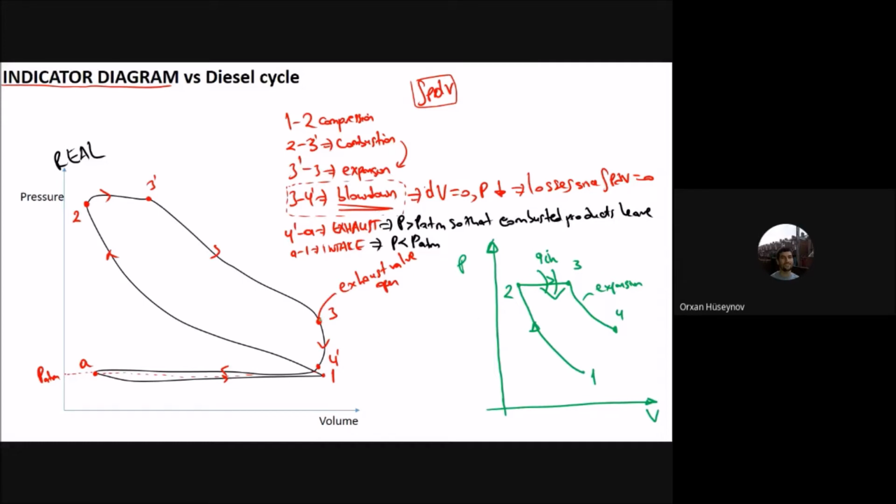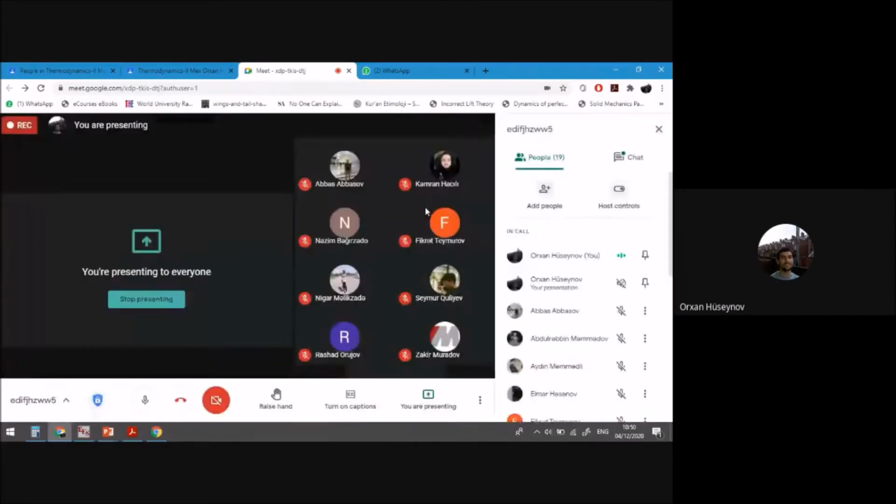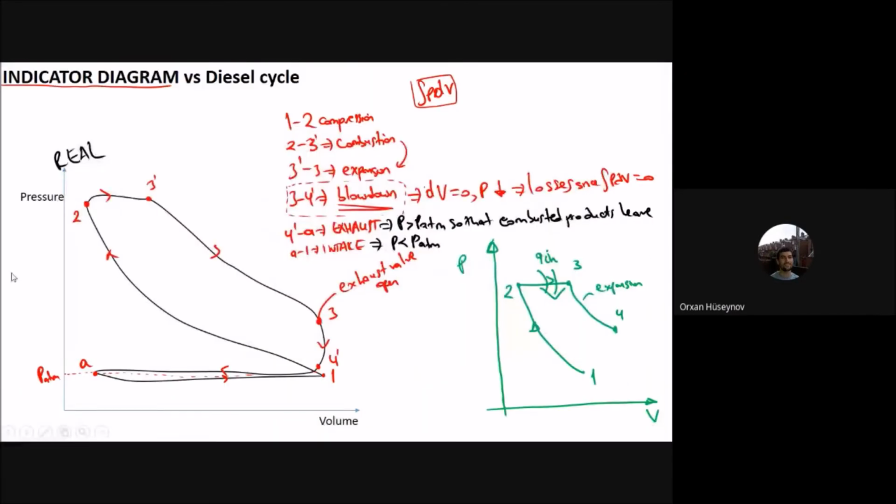And the fourth one, you should complete this cycle. Here you have the heat rejection at constant volume, but you should intersect with point 1 here. Let me draw one more line here. This one is point 1, and this one is the next stage, the compression. And here you have the Q_out.